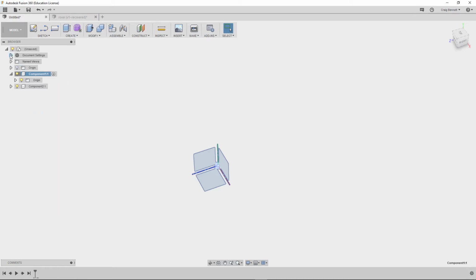Now as far as this goes, we need to set the units. If you want to change something else, I'm just going to use millimeters. And as far as movement, to move around on the screen, hold down the scroll wheel. To orbit, hold down shift and the scroll wheel, and you can lift up the shift after you start moving in orbit. And as long as you've got the scroll wheel down, it will keep doing this.